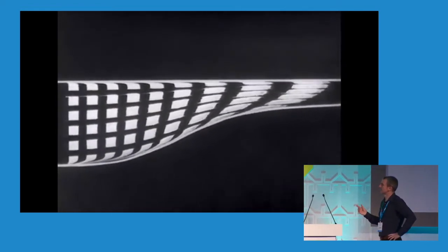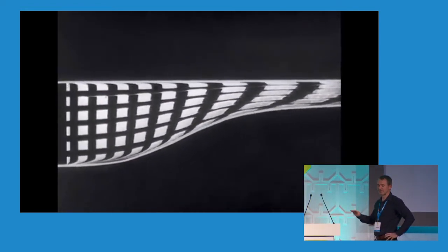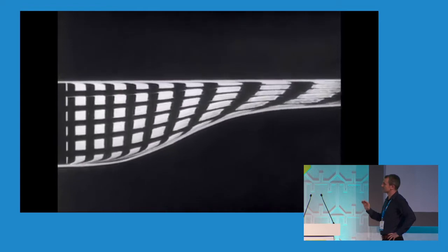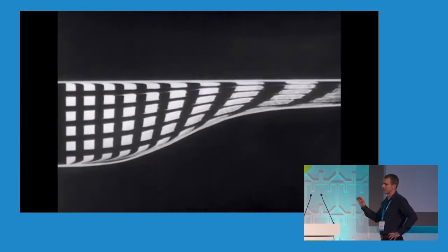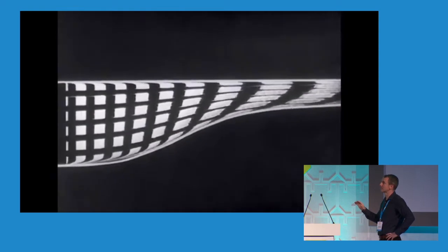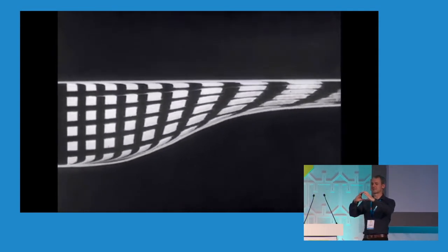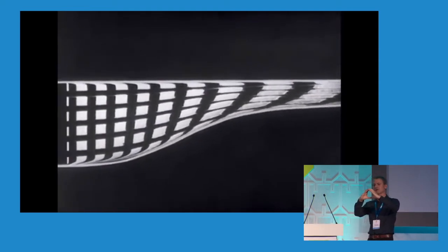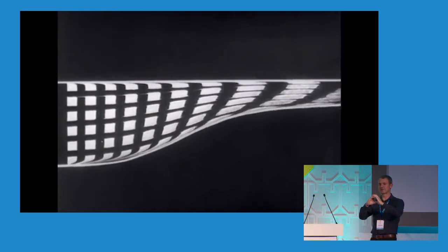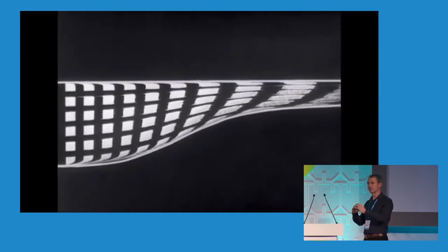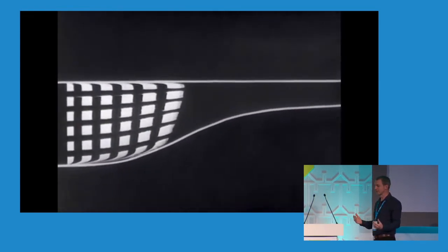So the key bit being that if you run this at about 25 liters a second, which is what most of our products sort of run at, that sort of region, you get a huge amount more losses from a pipe that is half the size. So to give it some context, I think we get about 68 pascals of loss, so don't worry too much about the units, through a meter of pipe that's 50 millimeters in diameter. So let's say it's about that big, 50 millish. If you halve that diameter down to 25, you get over 1,000 pascals in loss. So you get something in the region of 30 times the losses just through half the size of the pipe. So that's a really useful bit of information for us.